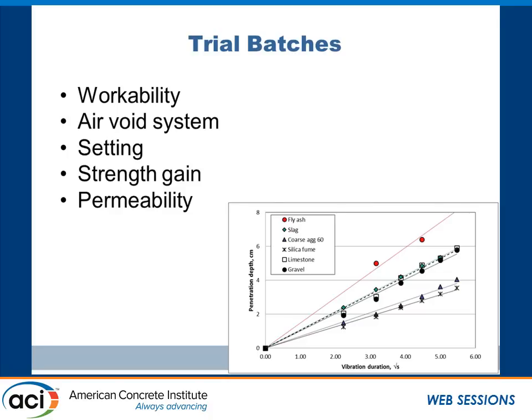Dave made the point already, and that's why I can stop here. You have to get into the lab and do trial batches. We're working with a test that measures vibration versus penetration of a fixed shape object. And what it's clearly showing me is that for different mixtures with very similar initial slumps, I can separate out the effects of fly ash, added water, silica fume, excess aggregate. I think I have something there. I'm not talking about it a whole lot. I need to do some more work. But I believe we have a method that will tell us how this system performs under vibration without having to pay $30 million for a slip-form paving machine.